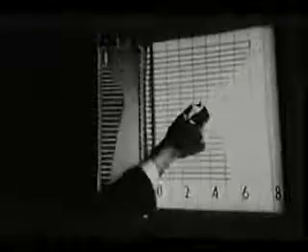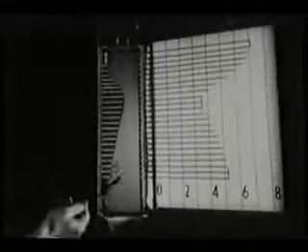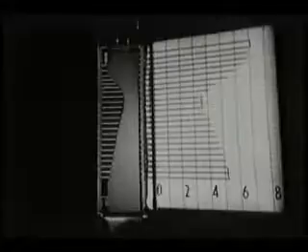At the upstream and downstream ends, where the cross-sectional areas are equal, the average velocities are also equal, and Bernoulli's integral would predict equal pressures. But the downstream pressure is actually somewhat less than the upstream pressure. This difference is due to viscous boundary layers, whose behavior we must always keep in mind, even when we pretend viscosity is absent.